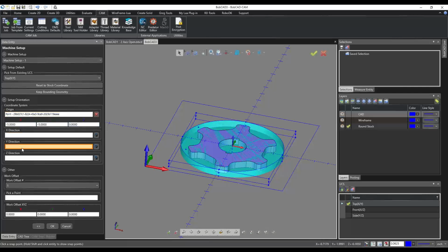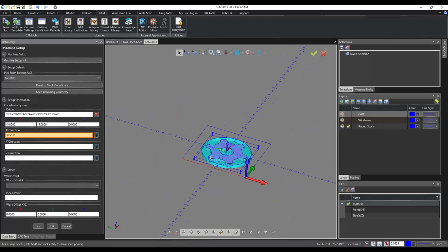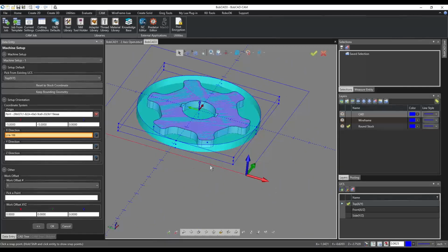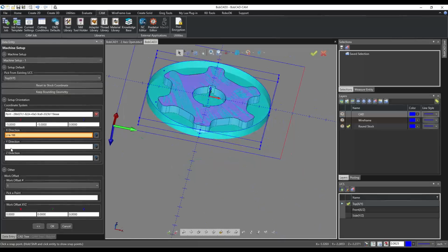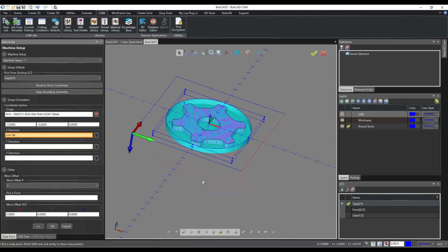And then also you can adjust the directions of the axes. So if I want the x-axis to go down here, down this line, I can select that line. And because of the right-hand rule, sometimes it goes the opposite way, but you just have to use these reverse directions until you get it into the right orientation. You can also select a line that's parallel to it. So instead of selecting this one, I could select this line. And you can see it still shoots down the same path. And so that's how those directions work there.